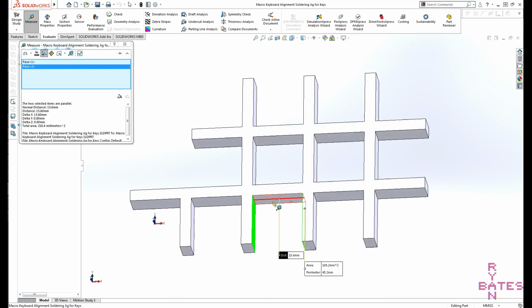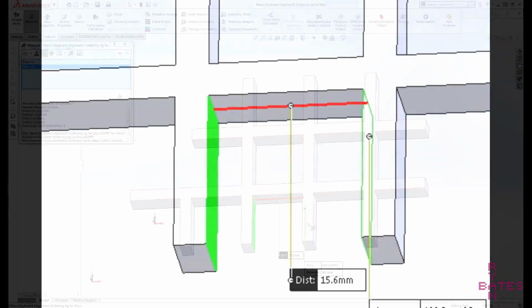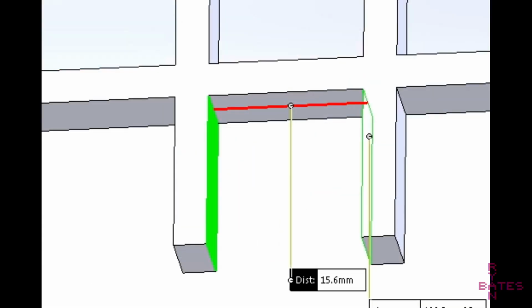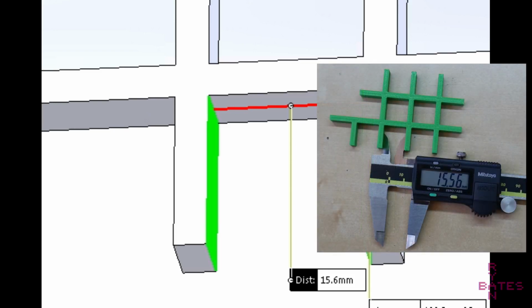Your model is printed with hot filament or plastic here. Once cooled, said plastic will shrink. On average, parts typically shrink by 1% when using PLA-based filament. This amount will vary based on the overall size of your part, its orientation, and again, the material that you're using